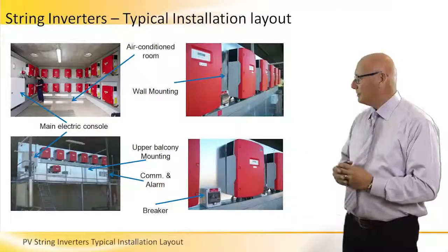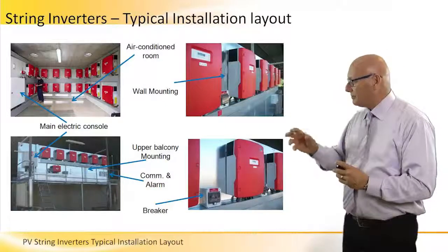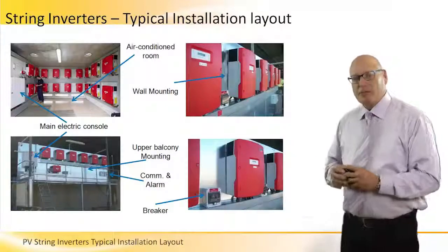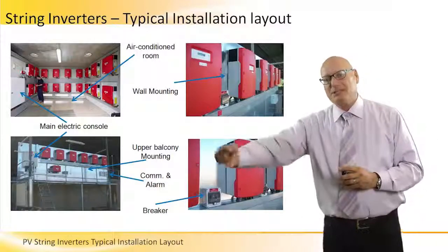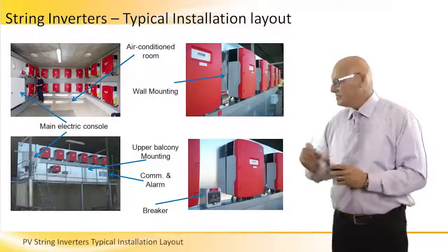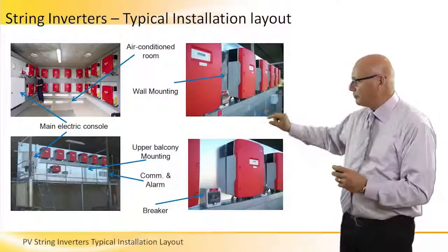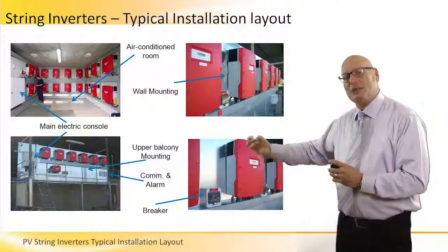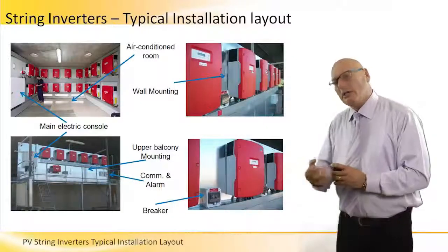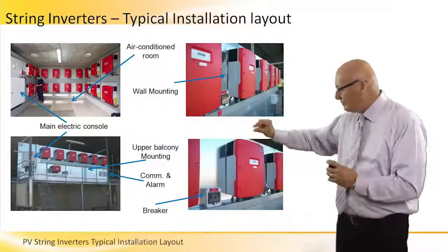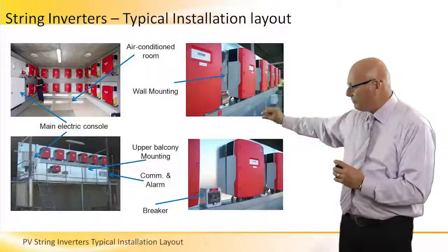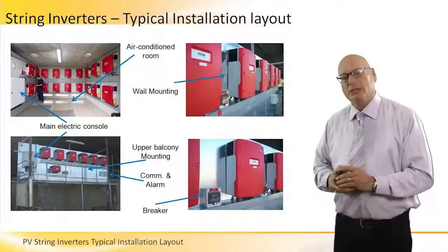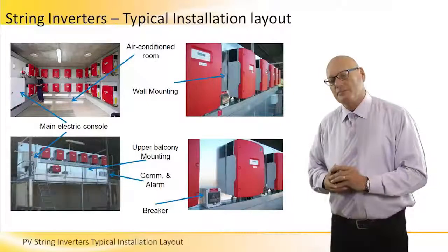Wall mounting. One string inverter after another, and they have a bus underneath them. This bus underneath them, in the top right picture, collects all the AC output energy and sends it in the metal bus to the main electric console.